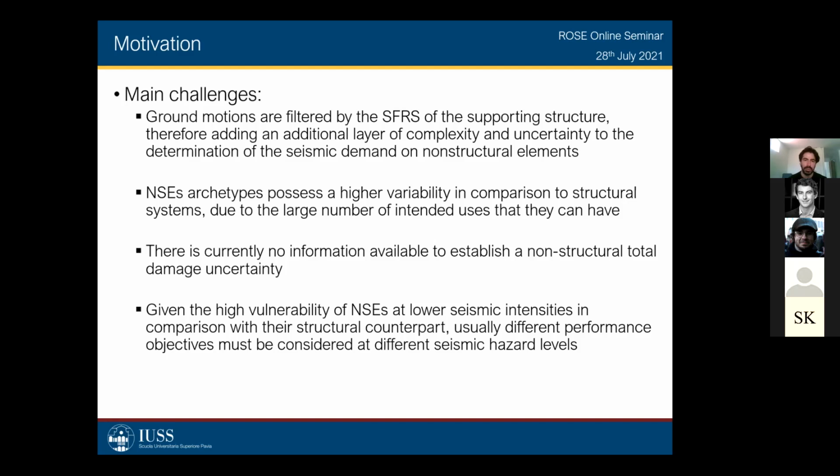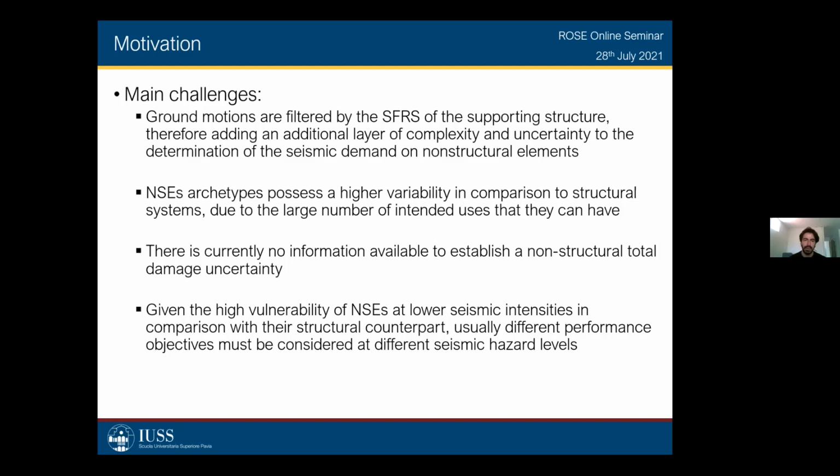The first one is that the ground motions are filtered by the seismic force resisting systems of the supporting structure. Therefore, this adds an additional layer of complexity and uncertainty to the determination of the seismic demand of non-structural elements. As those of you familiarized with non-structural elements know, in common practice we use floor motions for the design or evaluation of non-structural elements.